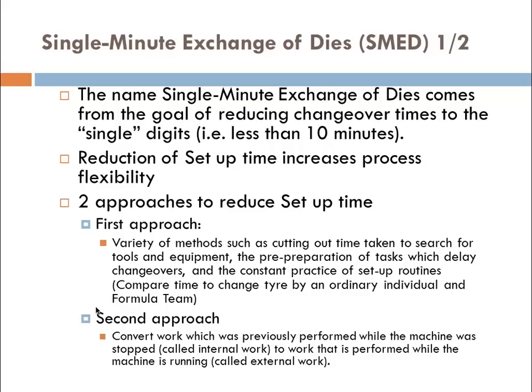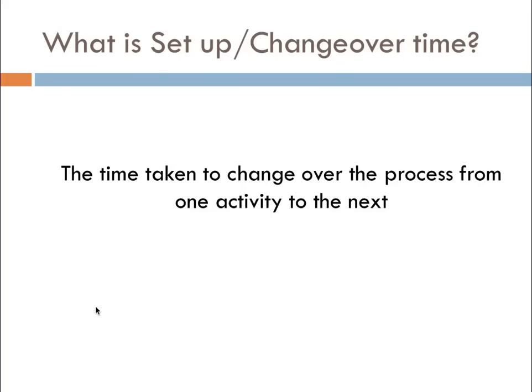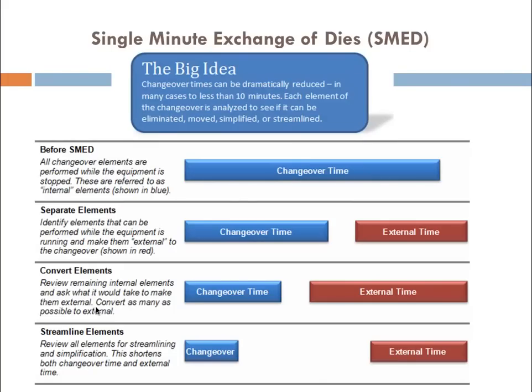There are again different methods of achieving the transfer of internal setup work to external setup work. As we have defined the setup or changeover time as the time taken to change over the process from one activity to the next, we can look at the big idea of SMED. The changeover times can be dramatically reduced, in many cases to single digits, which is less than 10 minutes.